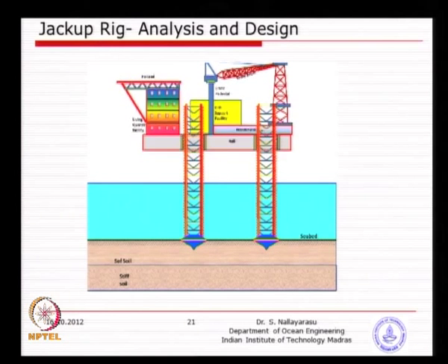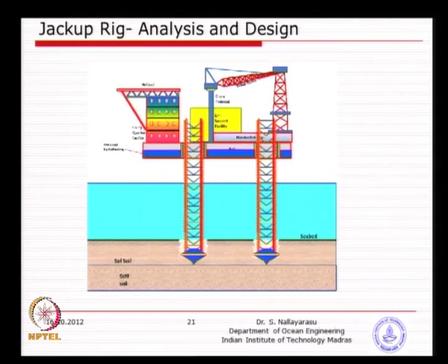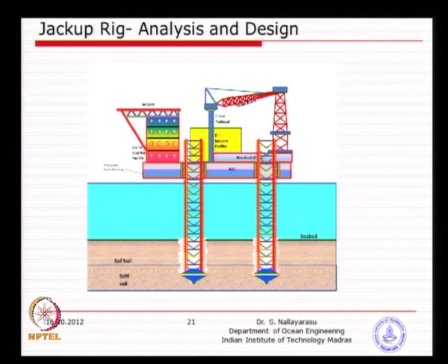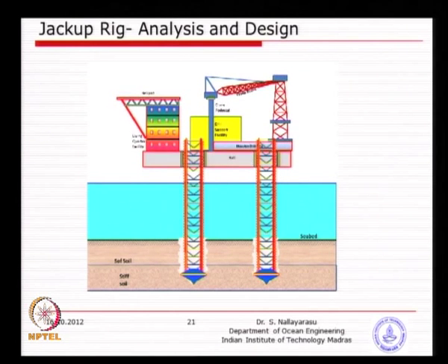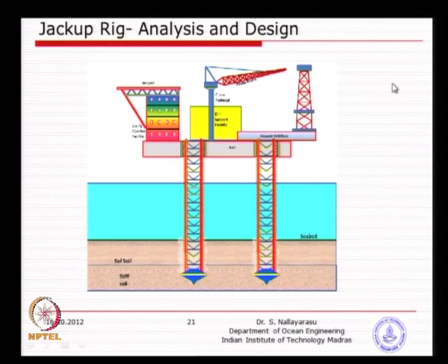Basically within those 2 days, if the environmental conditions are not good, you may actually retrieve back and then hold it on to floating mode, because floating mode is safer than partially penetrated legs. In floating mode you will always be stabilizing the rig with the tugboats, positioning it so that you do not lose the rig. After everything is done, then you can start drilling either near the jacket or at the open sea conditions.